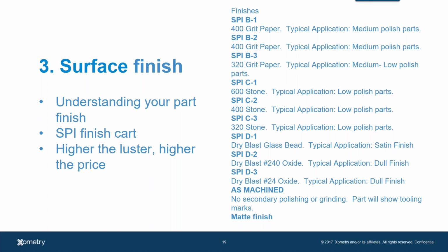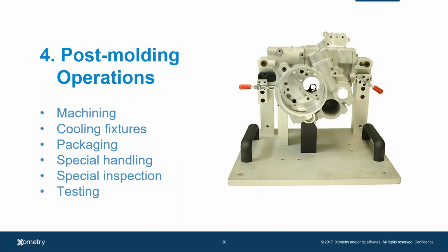If you've gone from our standard 125 surface finish up to 63 or 16, you see a huge jump in price, because we're slowing down and doing different processes to get that surface finish than just milling. Sure. And it does add a ton of time.